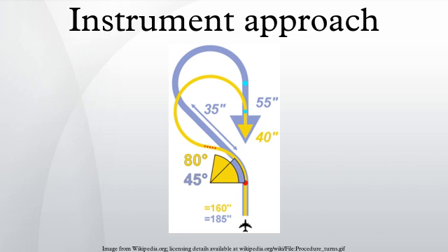This type of approach typically is found at smaller airports that do not have ILS approaches on both ends of the runway, where often the older localizer antennas are less directional. These transmit a signal from the back that is sufficient to be used in a back course approach. Newer localizer antennas are highly directional, and often cannot be used for a back course approach.